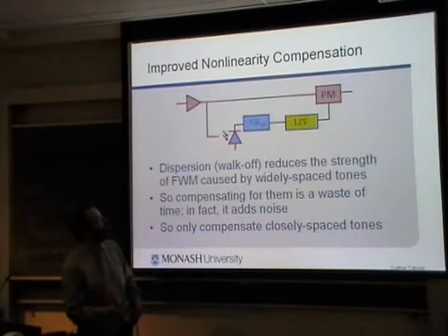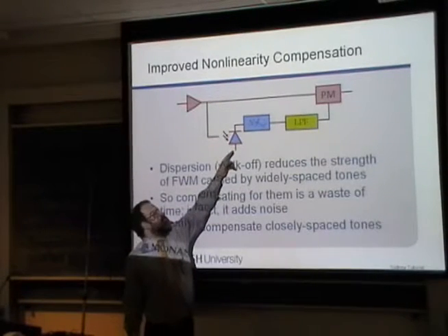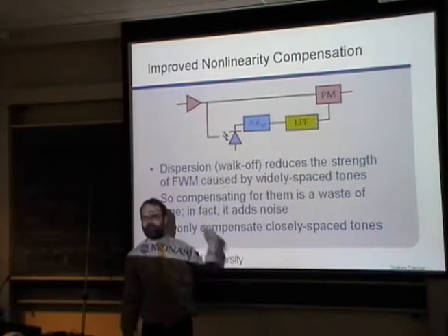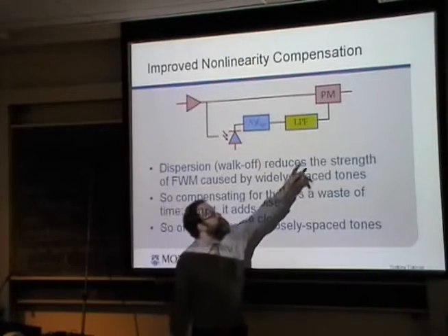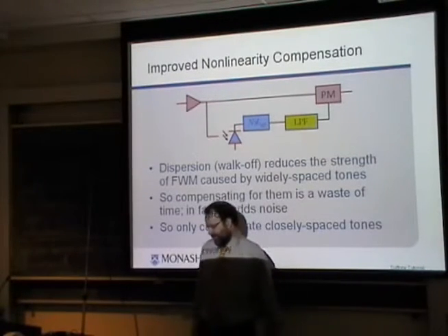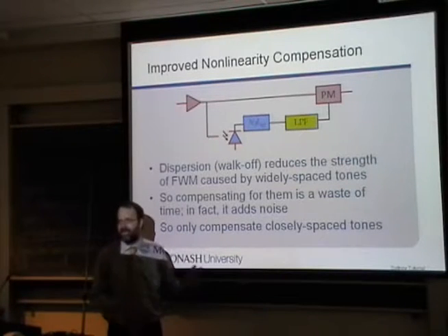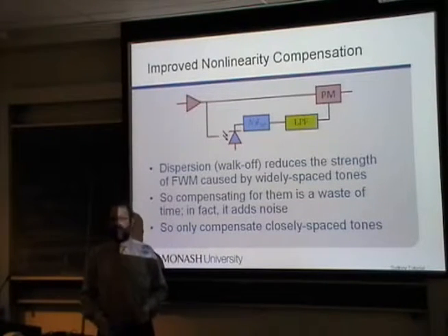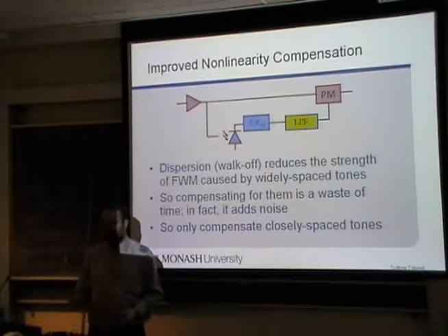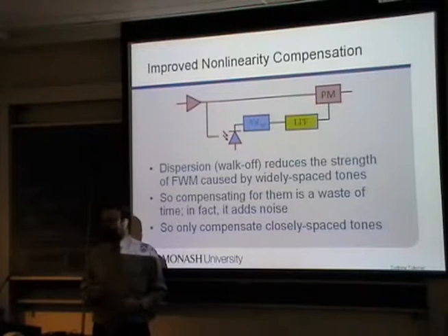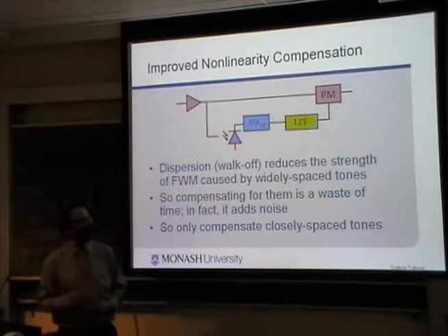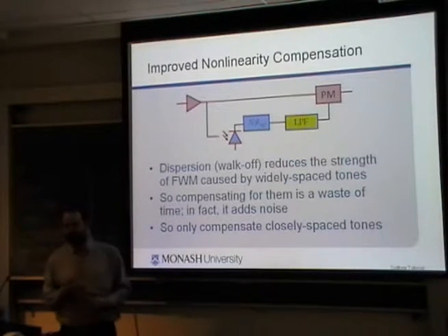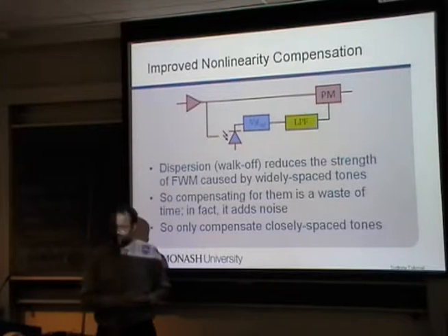And actually, it's even better than that. You can use a photodiode rated at 2 gigahertz rather than a photodiode rated at 40 gigahertz, and they're far, far cheaper. And you can use a phase modulator rated at 2 gigahertz rather than one rated at 40 gigahertz. And so using cheaper components actually works better. And I think that the first law of physics to me is if you want something to work better, you should spend more money. You never get anything for nothing sort of thing. There's no such thing as a free lunch. Well, this breaks that fundamental law of physics of something for nothing. So I think it's rather good.